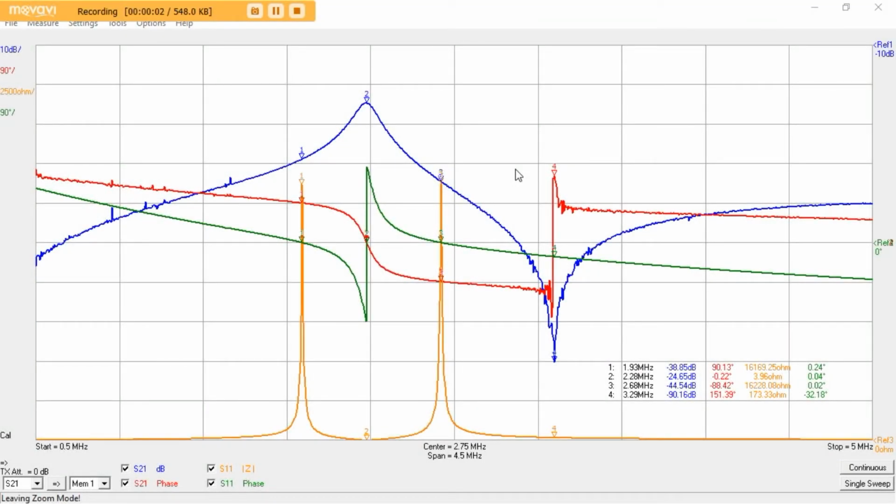Okay, I've now set the recording onto the computer screen of the VNWA, the DG8SAQ Vector Network Analyzer software. The experiment is currently set up at a 7 centimeter distance between the primary and the secondary, so that's fully closed as I showed earlier in the video.